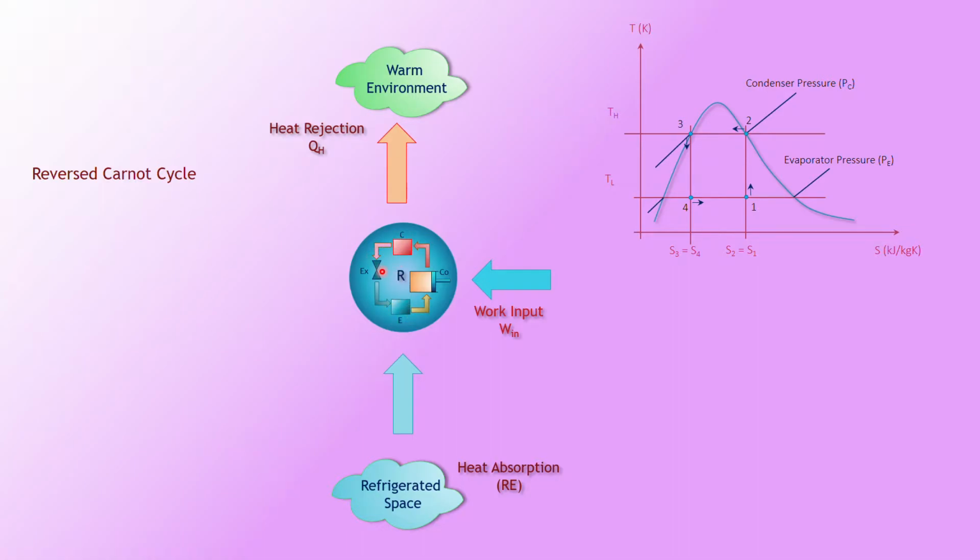And then in the actual case, this is an expansion valve. So this is your refrigeration cycle. On the TS diagram, it works based on the same thing, a square. It means that it is two isothermal processes and two isentropic processes.